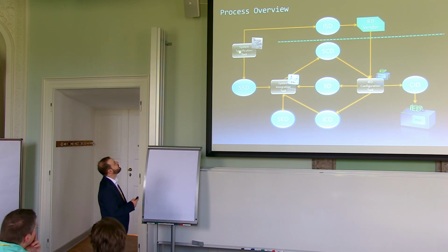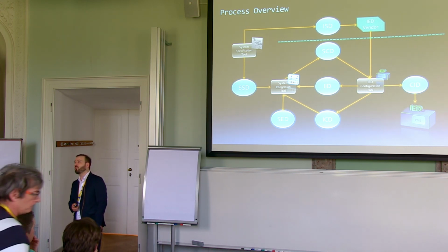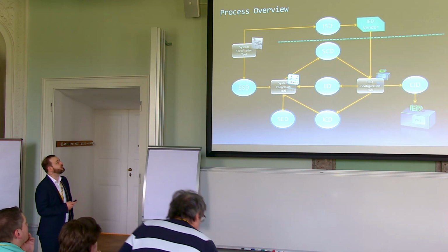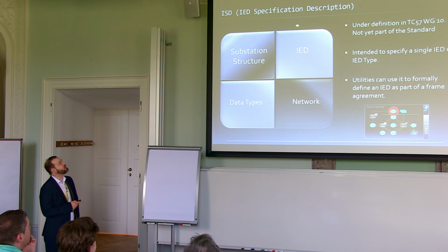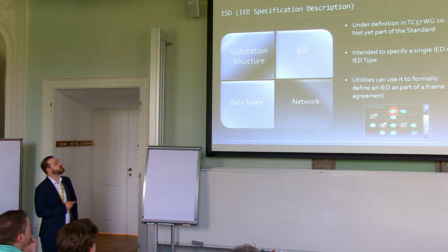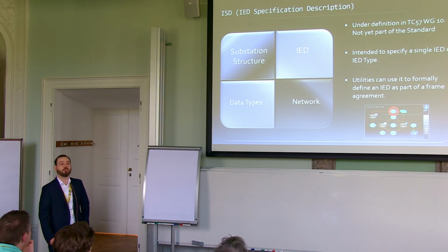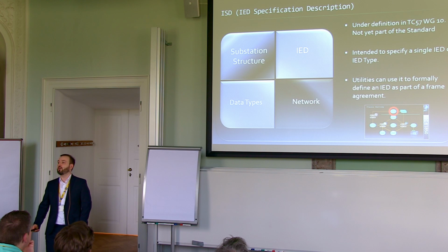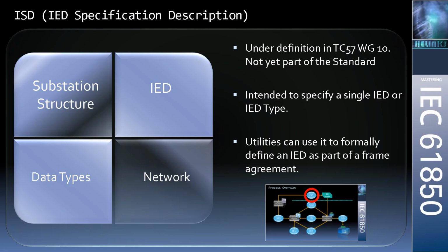You can see it's coming from a system specification tool, and it's connected to the IED vendors. So not specifically to a software, but rather to a vendor. And that is because the ISD is called an IED Specification Description. So it's not a real IED, rather it's an enumeration of the capabilities that you want to use in your substation, but you do not have a device chosen that offers these capabilities. So it's a specification of what a device should look like that we can use for this project.